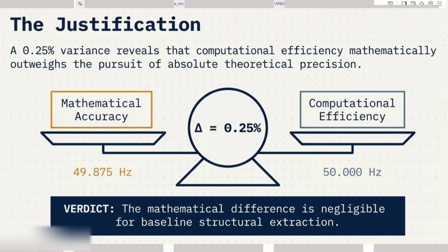If we use 5% damping ratio, we find our natural frequency reduces from 50 hertz to 49.875 hertz. That is a very negligible difference in the natural frequency. We always use the simple eigenvalue extraction, that is the standard modal analysis.